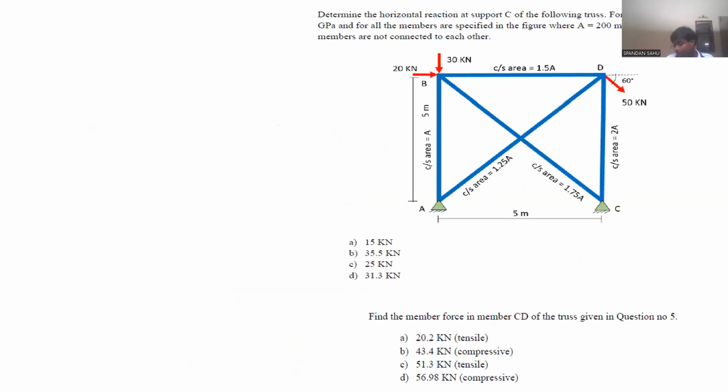Okay. You take this question, we will go to the last one. Now here in this question, as we are taking AE to be constant everywhere, here AE won't be constant. So I said at some point of time, you have to calculate the absolute value for each and every part when you are calculating that KPL by AE, and summation K square L by AE. So here you have to take the AE part and do it numerically.